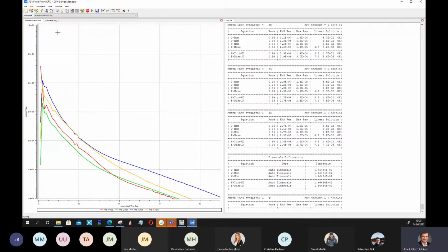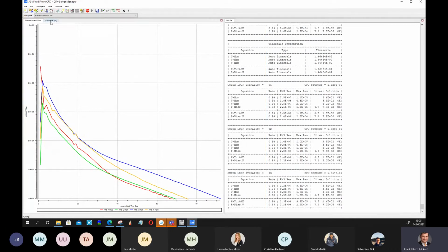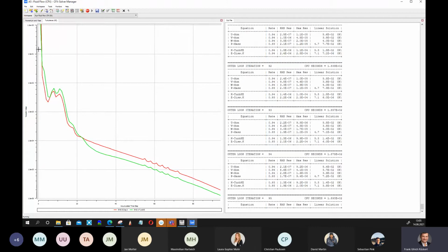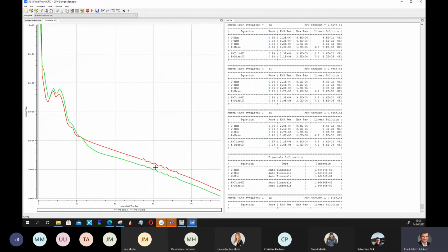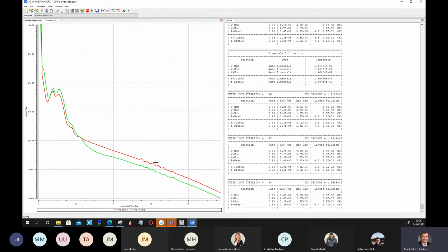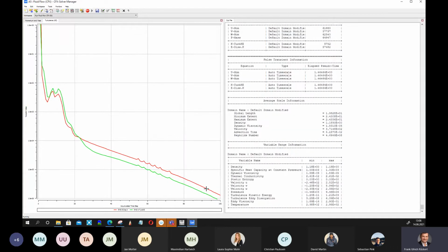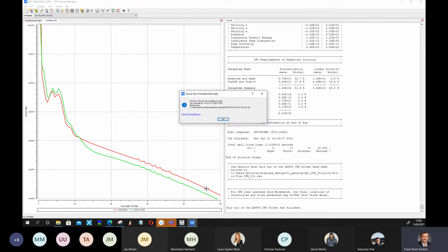A short look at the turbulence. I told you we decided to take the K epsilon model, and you can also see here the convergence of our turbulent kinetic energy K. We have also a balance similar to the Navier-Stokes equation, and we have also the dissipation and our balance equation for epsilon, the dissipation of the turbulent kinetic energy.